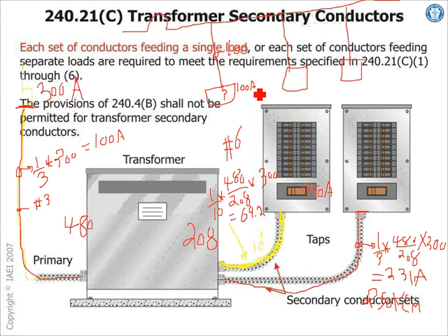Does that make sense? That comes in handy if you're doing farms and going from the service conductors at the pole and tapping from them. As long as you tie number 10 with a 30 amp at the end of it, we don't care. If you burn it, it's outside, right? Why do you think the code cares about tapping the conductors inside? You can burn the building. Any comments, guys, about tapping outside? Outside meaning underground or outside, as long as you're not inside the building.